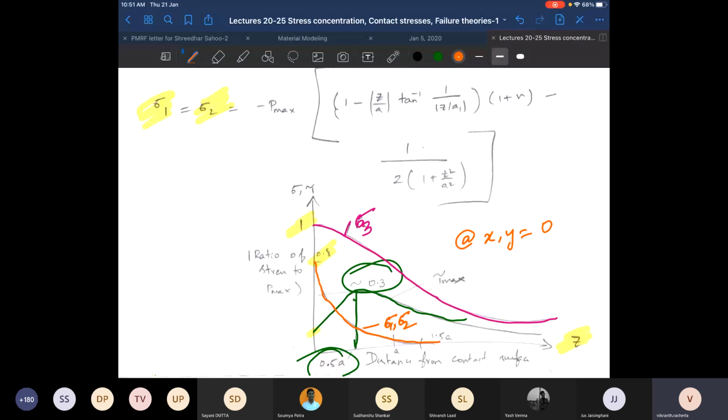If you have done a good design, chosen a strong enough material and are applying low enough loads, then you will not have ductile failure or subsurface failure. You may just have wear and tear on the top surface. But if your loads are high and you do not have sufficient strength, then you can have rolling contact fatigue, where cracks originate from underneath the surface and grow out to remove a chunk of material. I can in fact show you a picture.